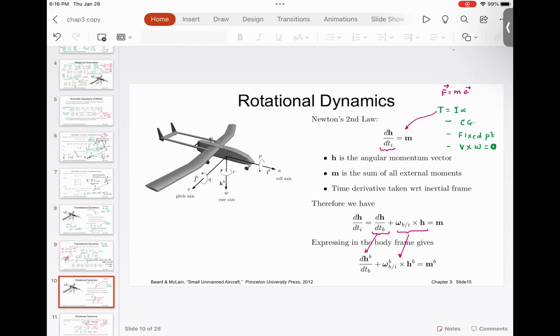At that point, when I discussed this, I tried to hint at it, but I want to make this point absolutely clear. This quantity is nothing but J, the mass moment of inertia. This is the mass multiplied by the radius of gyration squared. Since this is a point mass, we just have one length.